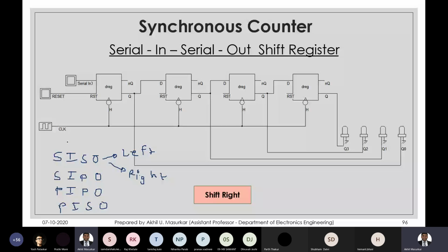Many times when you want to send the data, you are not receiving, you are sending the data. So your data is parallelly loaded into a shift register, and then it is sent out serially. That kind of operation is called parallel in and serial out. And many times one bus communicates with another bus in the form of parallel in and parallel out. So data is stored in a register and it needs to be loaded into another register. This can be done in a parallel fashion.